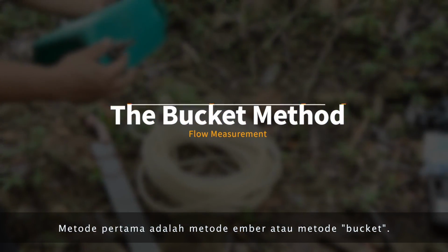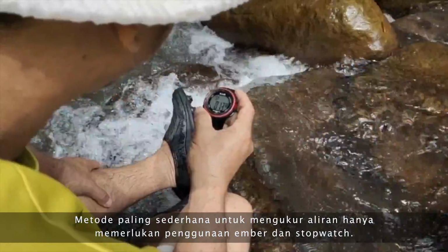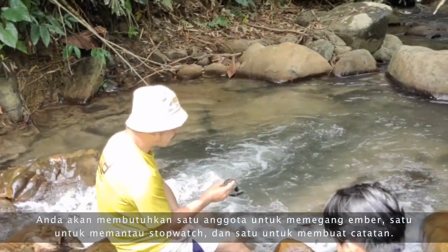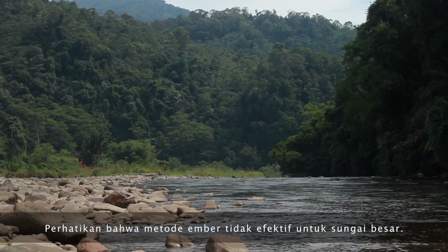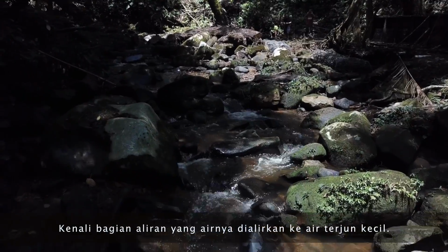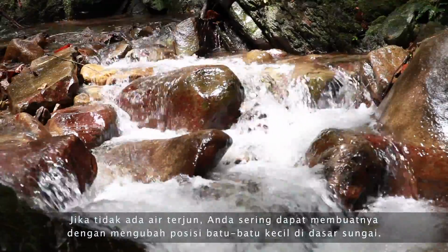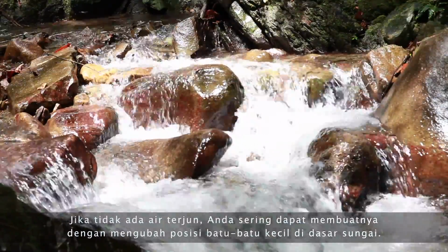First, the bucket method. The most simple method for measuring flow requires the use of only a bucket and a stopwatch. You'll need one person to hold the bucket, one to monitor the stopwatch, and someone to take notes. Note that the bucket is not an effective method for measuring large rivers. First, try and identify a portion of the stream where the water is channeled into a small waterfall. If no waterfall exists, you can often create one by repositioning small stones in the riverbed.